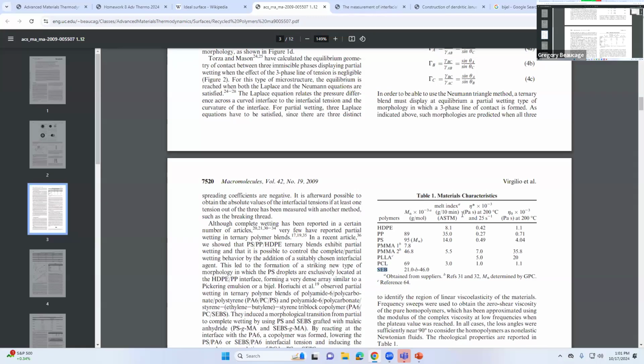Anyway, that's also called the plateau viscosity. So he's kind of looking for that number, and that number is this eta 0 number. So he measures that with the viscometer. Basically, this is a cone plate viscometer. You put the glue in there and you spin it, and you measure the torque. Usually oscillatory, but basically it could be straight. And then he plots that number here. So this is the plateau viscosity right here, Newtonian viscosity.